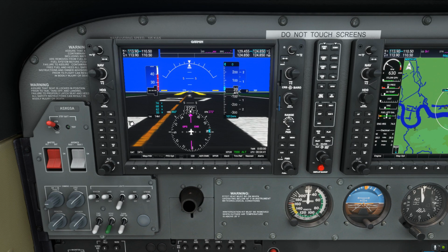If we press the flight director button, you'll notice a couple of purple lines will come up just above the yellow lines. It's basically a guidance system, the flight director. So if you're in autopilot mode, which I'll show you in a moment, and you're banking left or right, you'll notice the purple lines will bank left or right first. It's basically telling you, or the autopilot, this is the position. It'll be banking in a certain gradient. This is the gradient you need to position your aircraft in to follow the instructions you've just set up. I'll be showing you that in a moment.